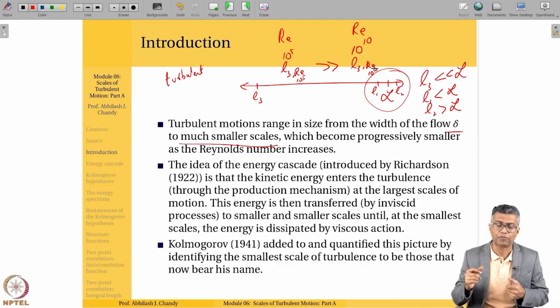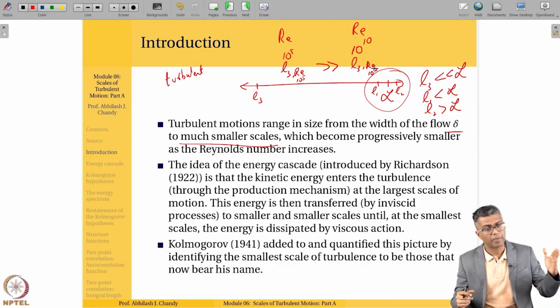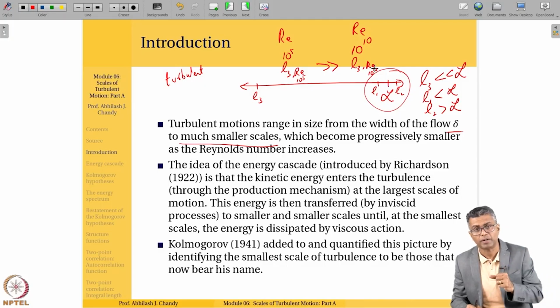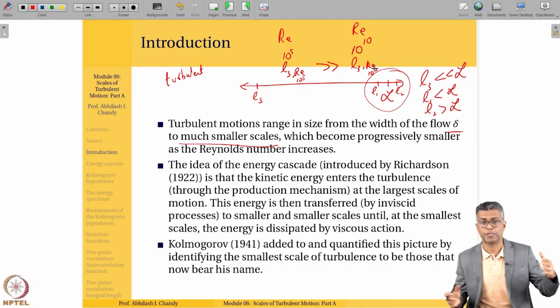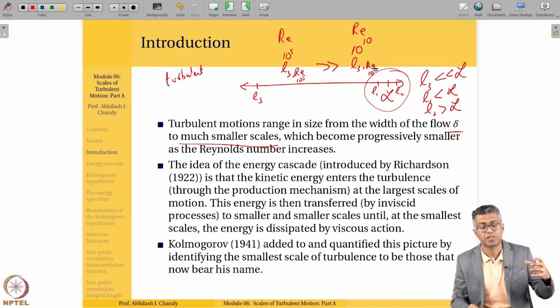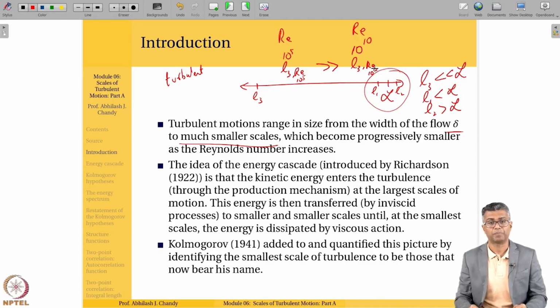If I take a channel flow, the flow is coming into the channel. I have turbulence being brought in. I have kinetic energy being brought in from the flow. It's probably coming in from a tank. It is coming into this channel. So the production mechanism is the kinetic energy that is being produced as the flow is coming into the channel.